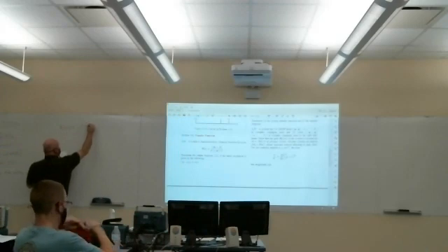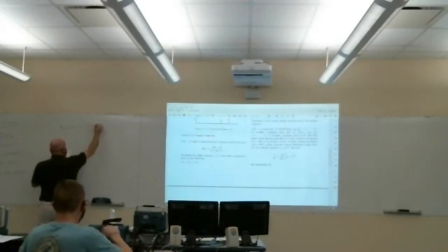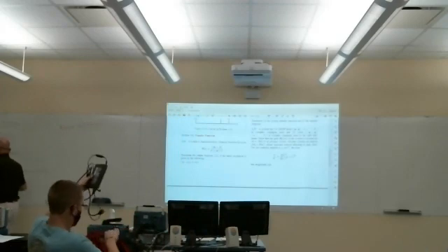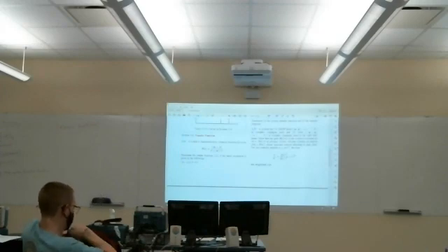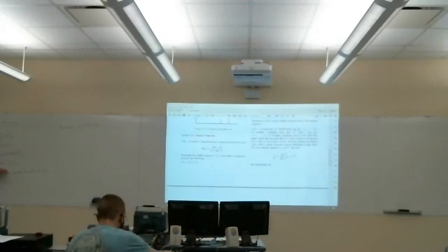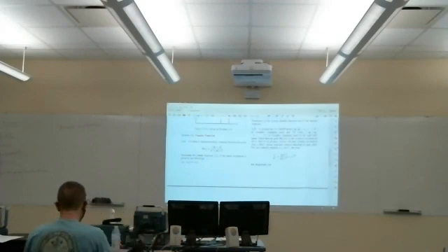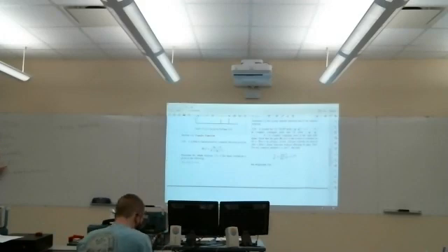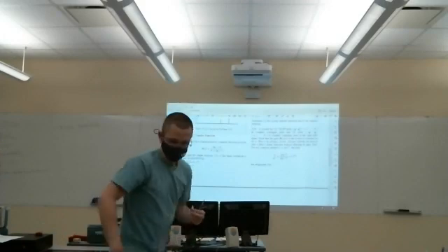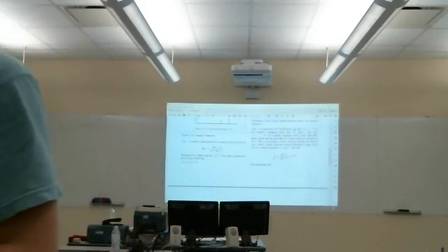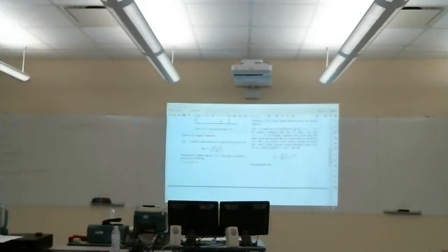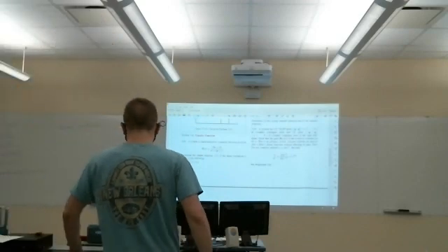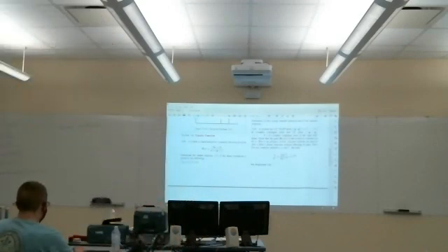So we're going to look at a couple of example problems. You can use this to solve for the output. The technique that we're going to use is to multiply the two transforms, the Laplace transform of the impulse response and the Laplace transform of the input, and then take the inverse Laplace transform of that product using partial fraction expansion. Sounds like a lot of work, but it's almost always easier than evaluating the convolution.